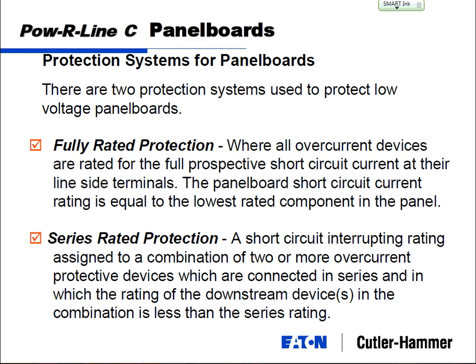Now, if I don't have 10,000 amps, and I have 65,000 amps available on my panel, well, this is a 3-pole 20. This one you can get in a 35 kAIC, 65K, or even 100 kAIC fault current. This one goes up to 100 amp max, this one goes up to 225 amp max, but they could be the same breaker for the same application, all dependent on the available fault current.